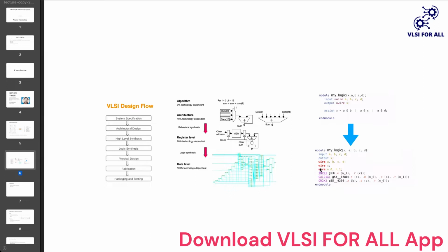So here you see wire, which is nothing but your regular wire connections between different gates. And you see something called INVX1, OAI21X1, or OAI21X2, right? Those are nothing but your technology gates, your inverter, AND gates, OR gates, some complex combinational gates and all that, which show what the inputs and outputs are for each. Correct? So in order to bridge the gap between our design and the physical implementation, that is where logical synthesis comes into the picture.